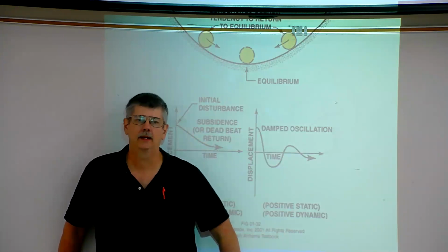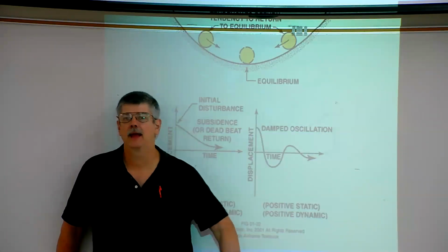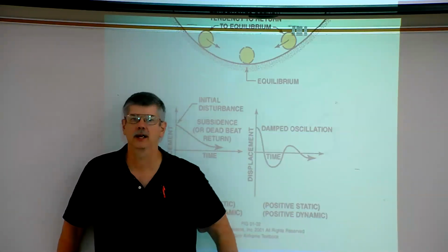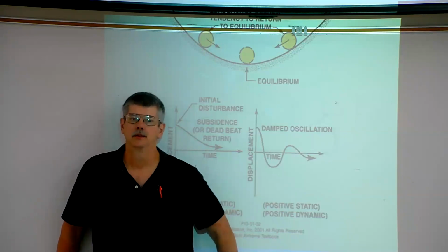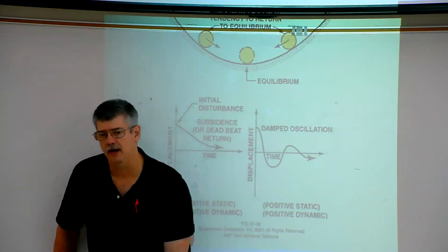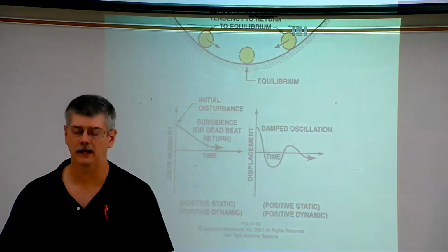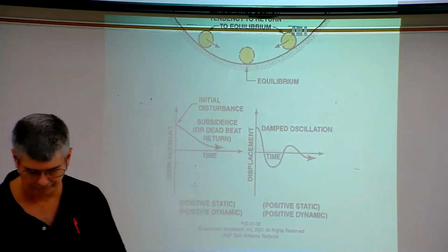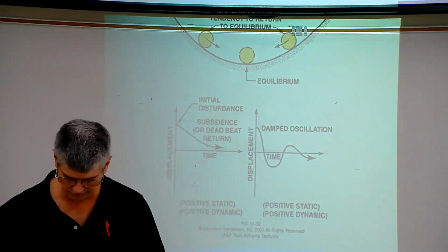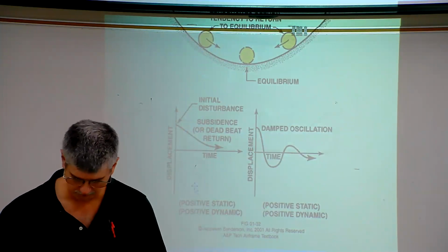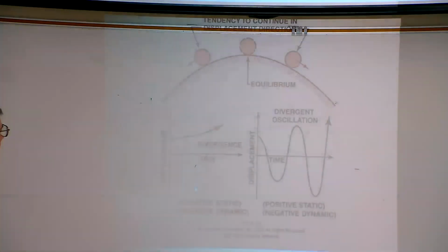The third way is what's known as an aileron rudder interconnect spring. When the pilot rolls the aircraft, say to the left, there's a spring that connects the aileron cable and the rudder cable, so the rudder would be pulled to the left. And thus, the aircraft would roll and turn to the left. Any questions there? No. Okay. All right, so we killed off quite a bit so far.